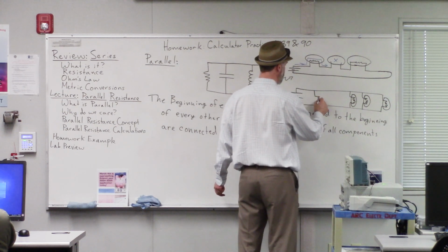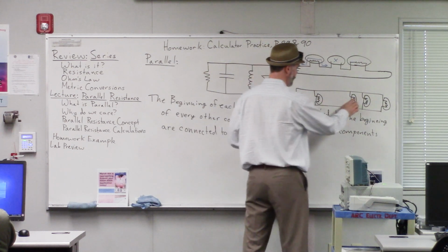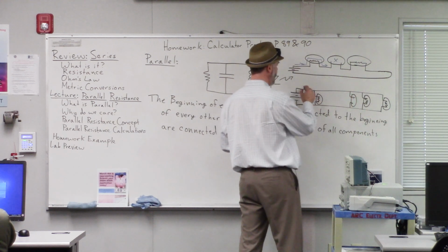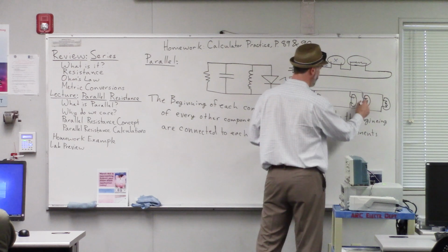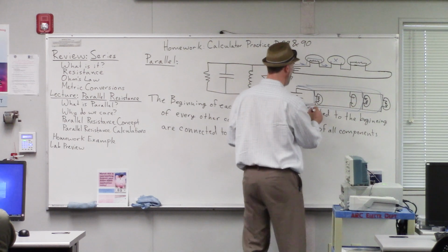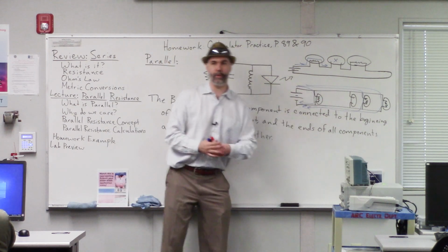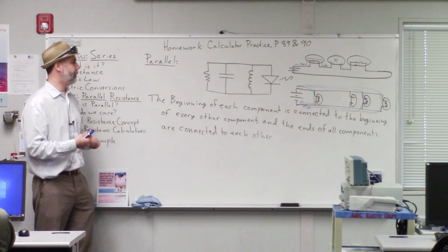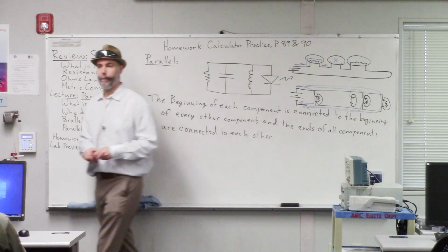And so now what happens is that if one of these lights breaks, say this one goes out, well, the electricity can't flow through that one anymore, so that one goes dark, but the electricity can still flow through the other ones. It can go through there and come back. It can still go through there and come back. And it can go through all the other lights, okay? So that's why these new lights don't go out if one of the bulbs burns, okay? The rest of the bulbs can still work. So in this case, a parallel circuit seems to be a much better way of doing this, okay?